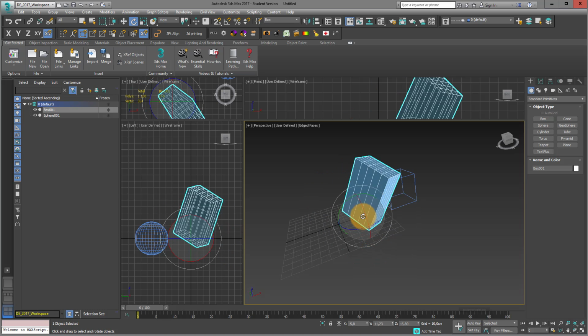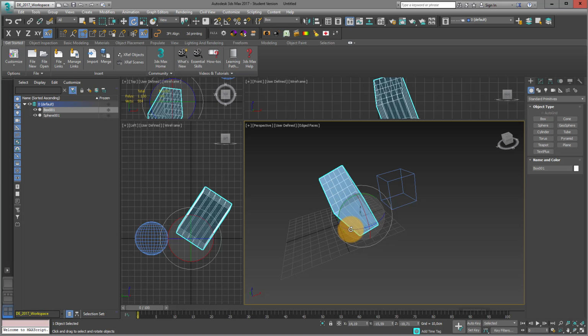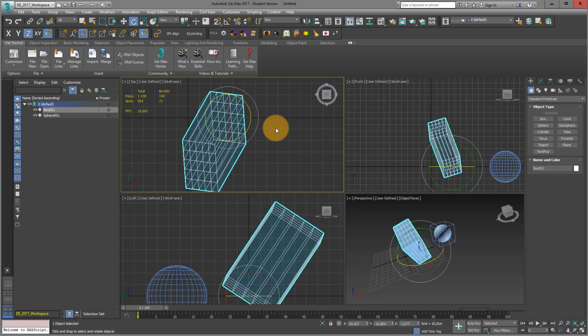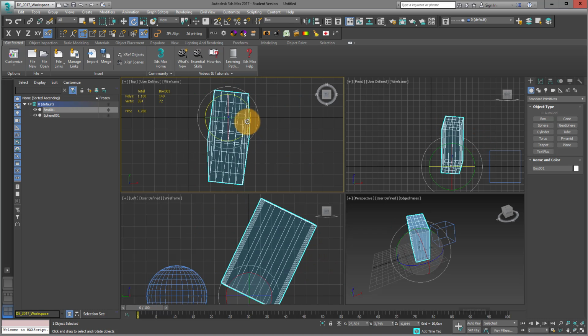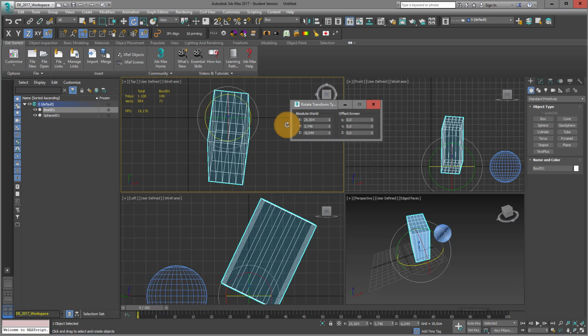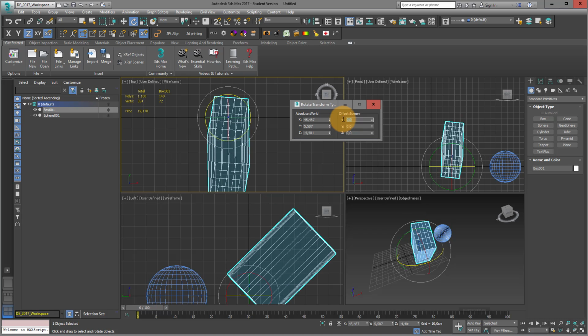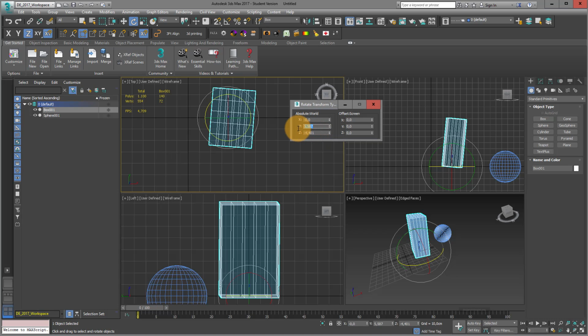And also here you obviously can do it when I select the top view, or for example if I select the left view, you can also do it in the other viewports. And also here, if you go on right mouse click, you have the transformations, so you can just from this position move it or rotate it again 20 degrees around the X direction. And if you just moved or rotated it by mistake, just go again in absolute mode and enter in X, Y, and Z 0 again, and then you are at the first position.